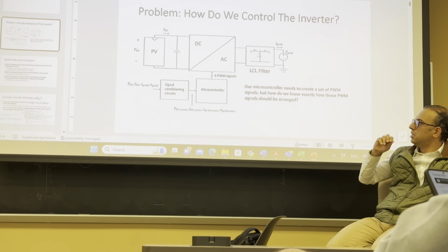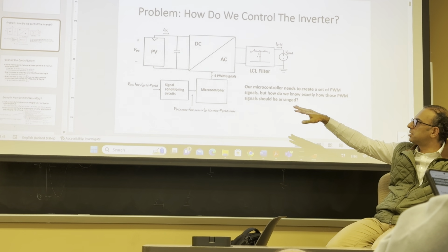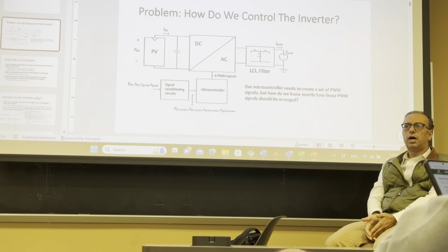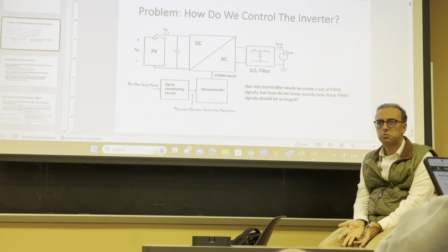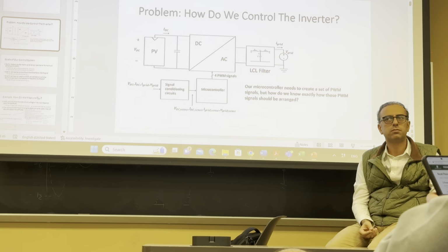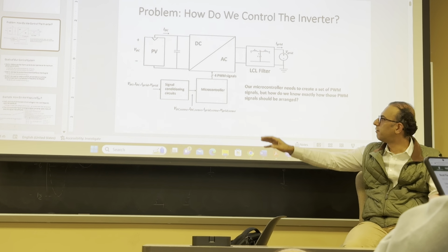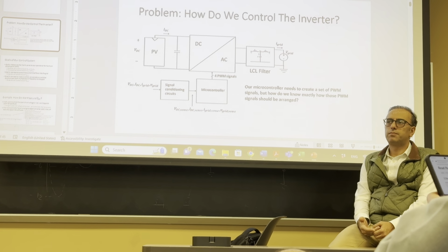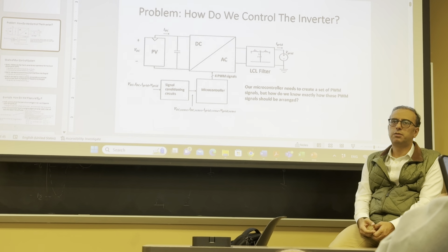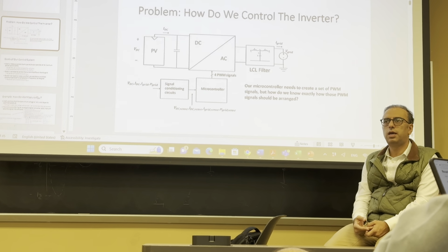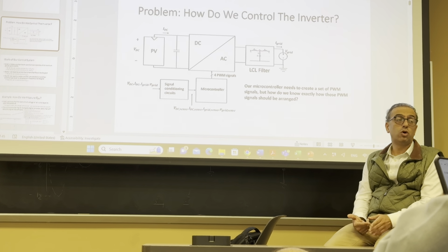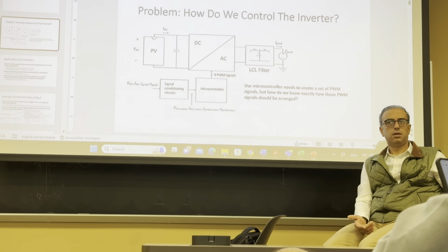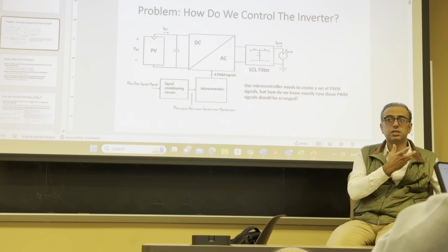So this information, basically the voltages and currents, is typically in analog form, so it's continuous, whereas the microcontroller is a digital interface. Therefore, either the microcontroller can provide the A-to-D conversion, or you do it, or the sensor has it built in.